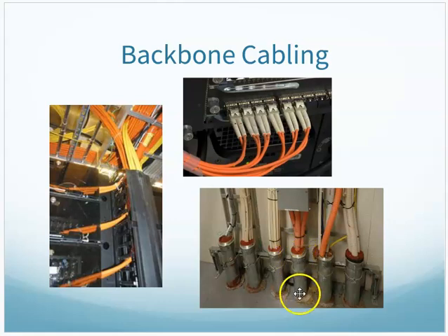That's actually a hole drilled through the floor and a conduit going down through, and fiber links going down through with the red clay as fire stop, which keeps fire from one room traveling through to the other room. That's a fire retardant clay in there called fire stop. So that's typically your